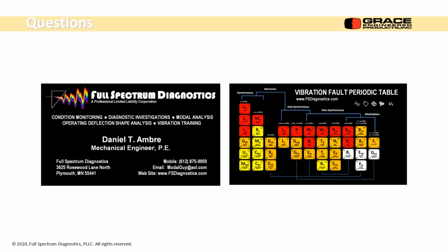All right. For the example you used, would the AMCA standard be used to set the alarms with the bearing clearance? AMCA, bearing clearance. I assume we're talking journal bearings again. And send me an email if I'm wrong, but usually you set your gaps for journal bearings with proximity probes at whatever the manufacturer says is half the internal clearance of the bearing.